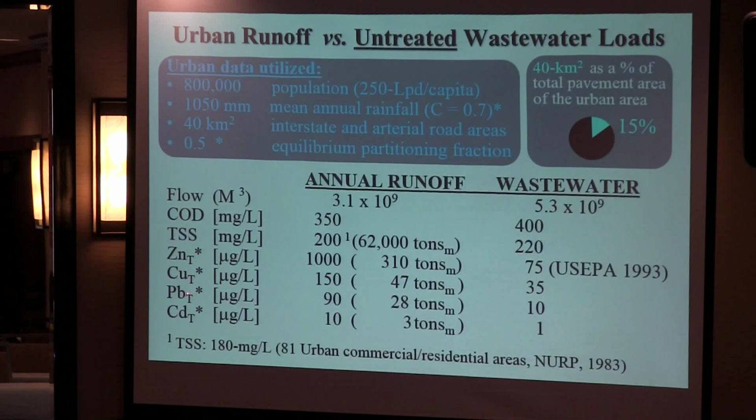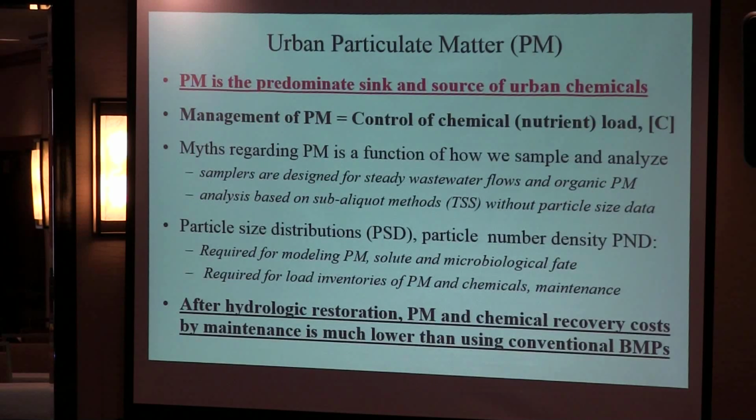Total zinc, copper, lead, and cadmium, total being the sum of the dissolved and the particulate fractions, however, in annual runoff is much, much higher than what we see in domestic wastewater. We wouldn't think of ever discharging wastewater untreated, and yet we do so with runoff every single day. The magnitude of the problem is actually greater than wastewater treatment.